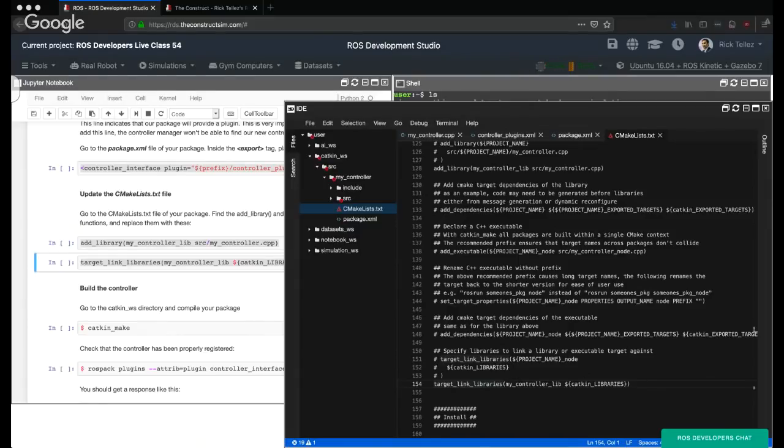No, the differential drive controller that Daniel is suggesting is for a 2-wheel robot. You could probably also use it for your autonomous robot with 4 wheels, but the proper one is the skid steer one. So check for that one and try it.